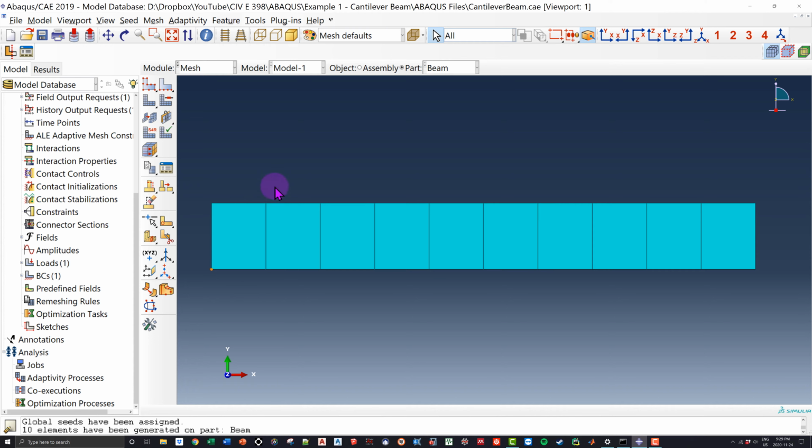Next, if I know the displacements everywhere, I can go inside of this element and actually calculate those stresses and strains. So that's what's happening inside of the element. This actually gets very complex. I'm not going to dive too deep, but here's the key takeaway. The finer the mesh, so the more little squares we have, the better the accuracy.